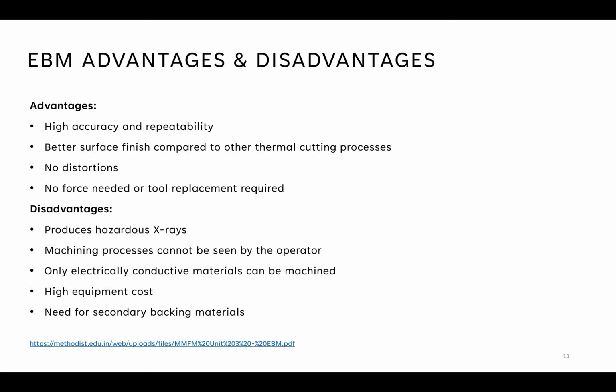The disadvantages, however, are that it produces hazardous X-rays, which are very harmful for the operator. Therefore, the machine is operated in an enclosed space and therefore requires very skilled operators to work it. And the operator also is not able to see inside the machine as it is operating. Only electrically conducting materials can be machined, so this means a lot of regular plastics and ceramics are not applicable for this process. The equipment cost for this machine is very high since it's such a specialized type of machining, and it also needs secondary backing or sacrificial materials to function.